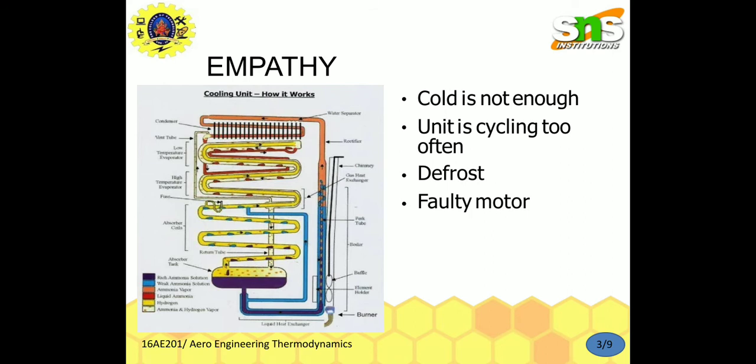The cold liquid vapor mixture then travels through the evaporator coil or tubes and is completely vaporized by cooling the warm air being blown by a fan across the evaporator coil or tubes. The resulting refrigerant vapor returns to the compressor inlet to complete the thermodynamic cycle. The above discussion is based on the ideal vapor refrigeration cycle and does not take into account real world effects like frictional pressure drop in the system, slight thermodynamic irreversibility during the compression of the refrigerant vapor, or non-ideal gas behavior.